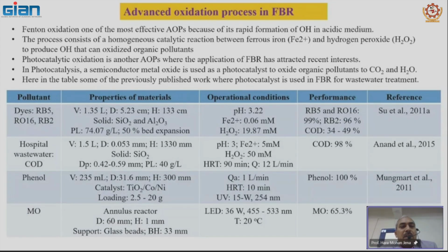Then photocatalytic oxidation is another advanced oxidation process where the application of a fluidized bed reactor has attracted a lot of interest from researchers, and its use in industries is also there. In photocatalysis, a semiconductor metal oxide is used as a photocatalyst to oxidize organic pollutants to carbon dioxide and water.